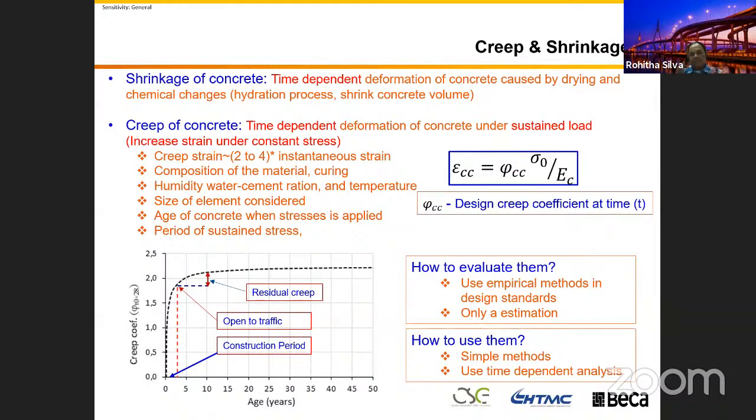Because in the bridge, you're going to install this expansion joint before you open it to the traffic. You build everything, you build your barrier, you build everything, then only you come and build your expansion joint. So the installation time is quite close to the opening time.